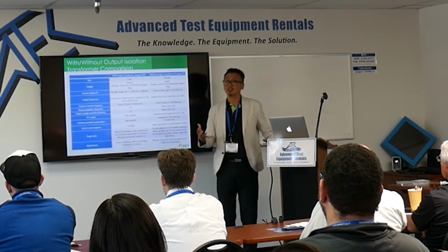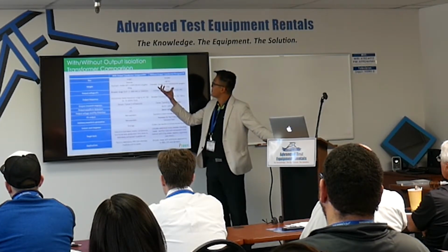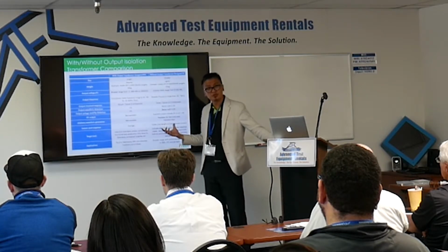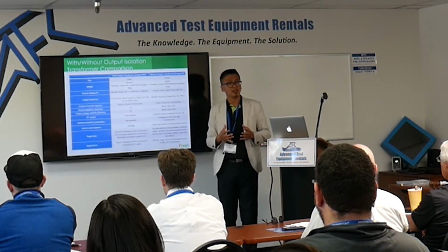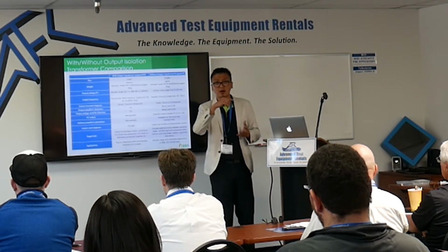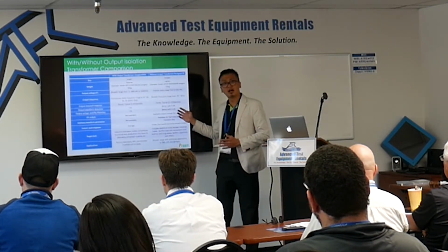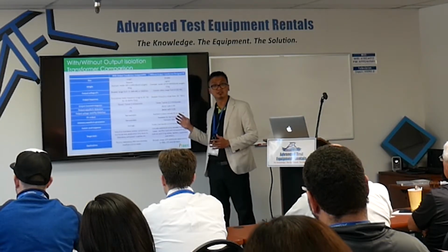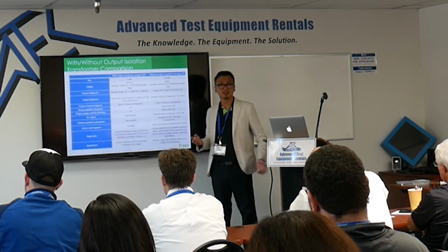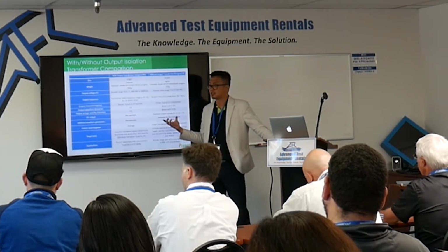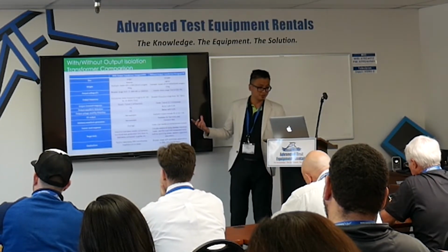Nobody can make like a 15 to 5,000 hertz with isolation transformer because nobody can do that kind of transformer in the world. But without output transformer, the good thing is that if you want to test something with arbitrary waveform, harmonic waveform, without isolation transformer, it would be easier to do that. Like a transient test, that would be easier to do. So it's a totally different application.